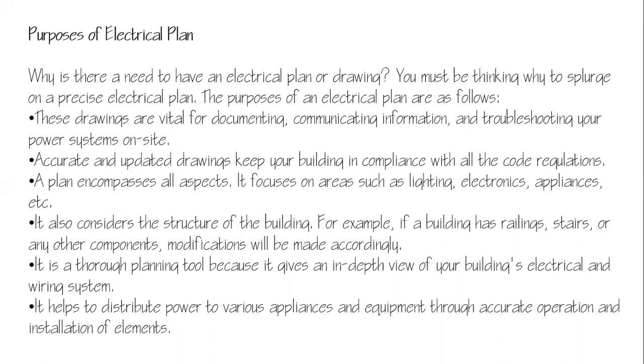So maximum loading would be for appliances of 1000 watts and up. You need to have a separate circuit for that one, just to avoid overloading. So basically, if they are just power outlets, it's okay with 4 to 5 outlets on a single circuit. So that's advanced electrical planning already, since it's more on calculating the capacity, the wattage of your circuits.